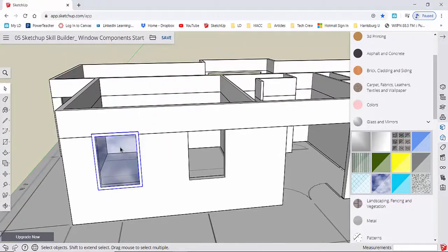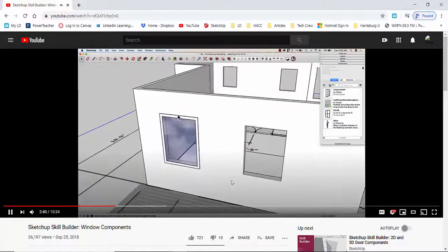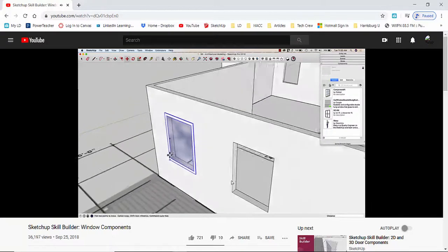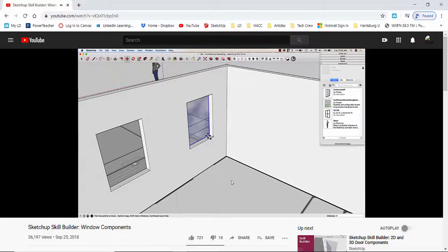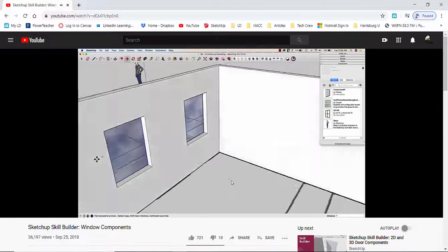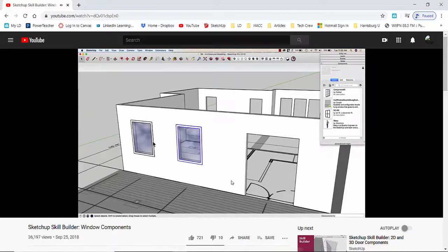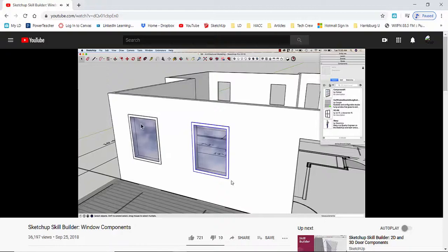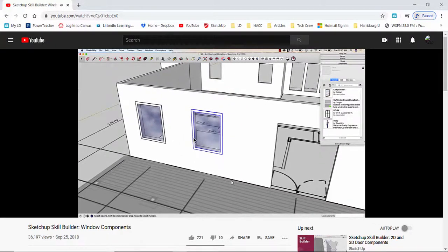Make sure you only have one group, not a group inside of a group inside of a group like we did with the walls. Layer. That is a simple solution, and again, that's going to work. In this case, I could actually take that and option-copy it over, throwing it onto another opening. In some situations, that might be enough. I don't have mullions in here or anything like that, but drawing those separations is pretty simple. But that's the basic steps I might use.